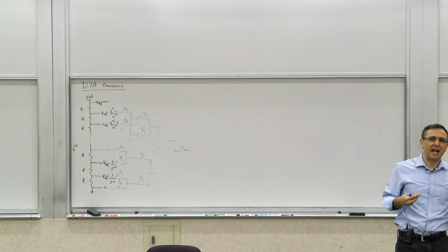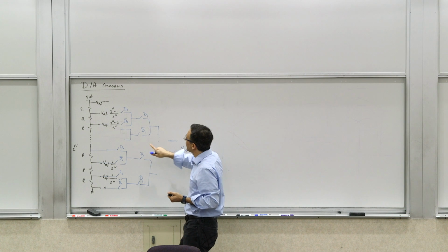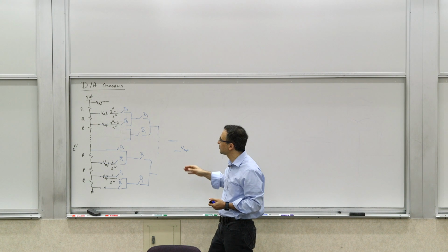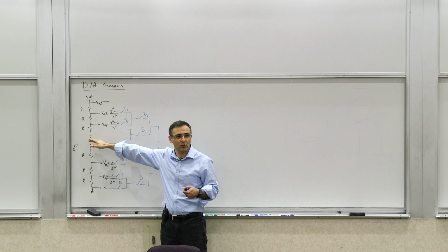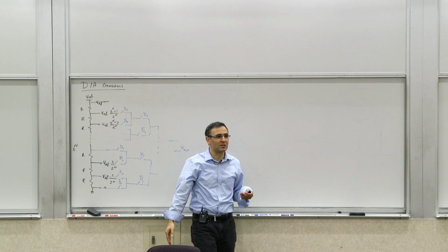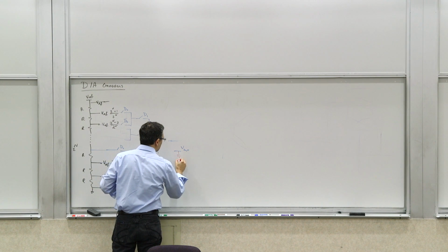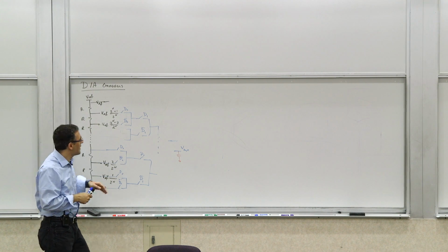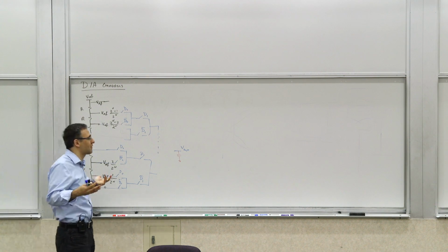So this may sound simple and relatively straightforward, but it has several problems. Obviously, it has no driving capability. You're looking at some sort of a passive network. You will have a time constant that would depend on where you connect. Because if you connect in the middle of this branch, if your voltage is around here, you have two large resistors on both sides. If you're at one of the ends, you have a smaller resistance, so you have a different time constant associated with the inevitable load capacitance that would be here. Also, you don't have drive capability, so it would be slow. There are other questions about this, of course, the quality of the matching and all those things, but this is some sort of a D2A, right?